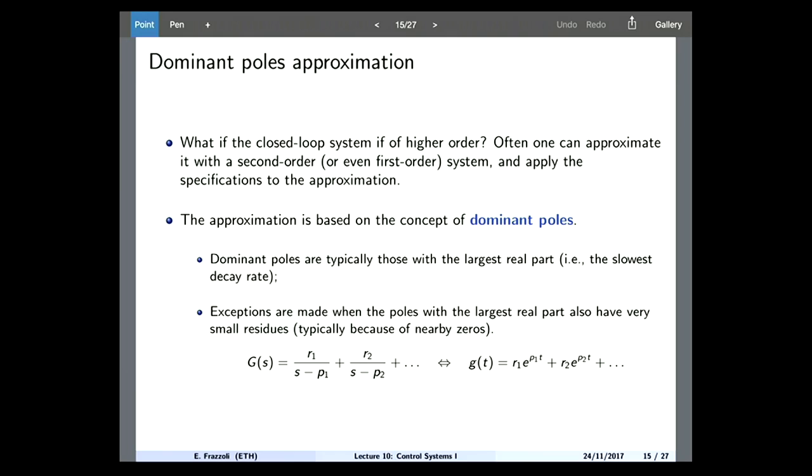So essentially what I meant is the poles that are closest to the origin, the ones most to the right. So it's either the smallest magnitude if they're negative, or the largest if they're positive, right? If I say just the largest, that captures both cases. So it's the poles that are furthest to the right. Okay, thank you, good point.